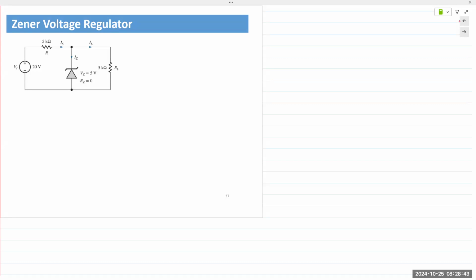As I stated, once we have our rectifier circuits, we convert AC to DC and apply a filter capacitor. The filter capacitor will still have some ripples. But if you connect a Zener at the output of that capacitor, the Zener will regulate the input voltage and provide a near constant output voltage. A flat line, constant voltage, meaning a pure DC level.